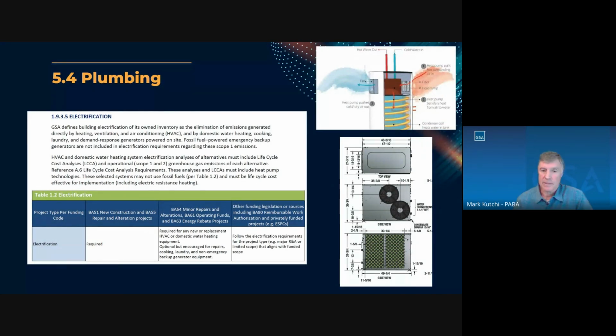And I know it's not a condensing unit, but the one example I showed, this heat pump water heater, it's hard to tell here, but the fan and the intake are on the sides of the unit, and this unit is intended to be ducted, discharge air ducted outside of the building.